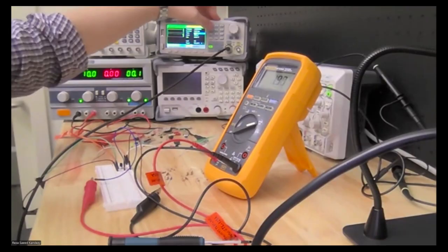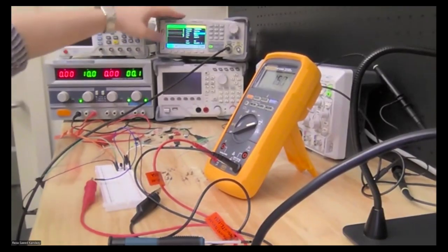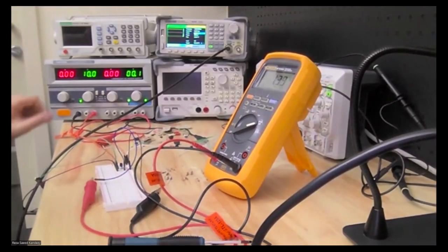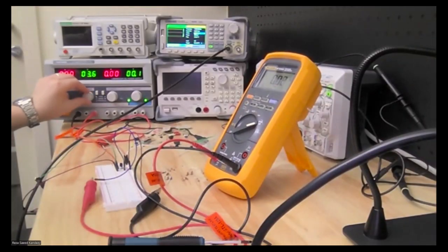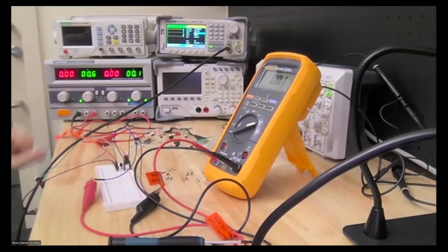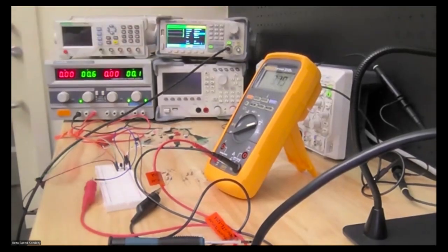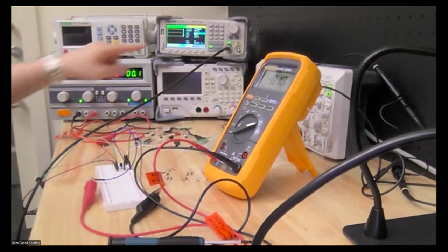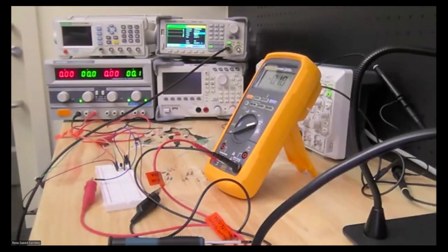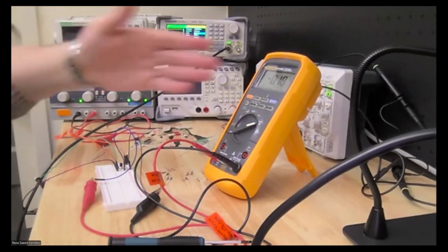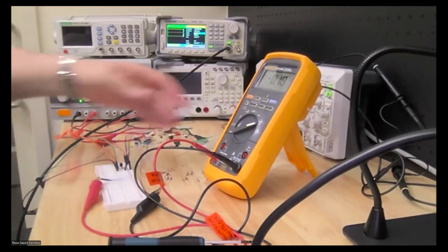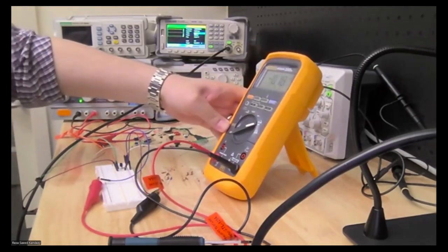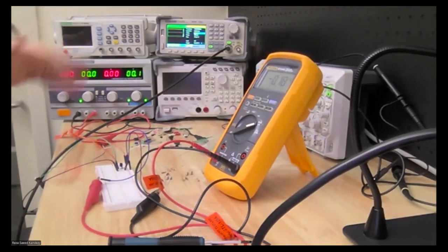If it's 5 volts, that means we have a 2.5 offset. Now I'm going to change my DC source between the drain and source to 0. I am going to apply the voltage to the gate. So now the switch is on, but there is no voltage between drain and source, so it shouldn't show any current, but it says minus something, which is an error. It is an offset error or leakage somewhere.